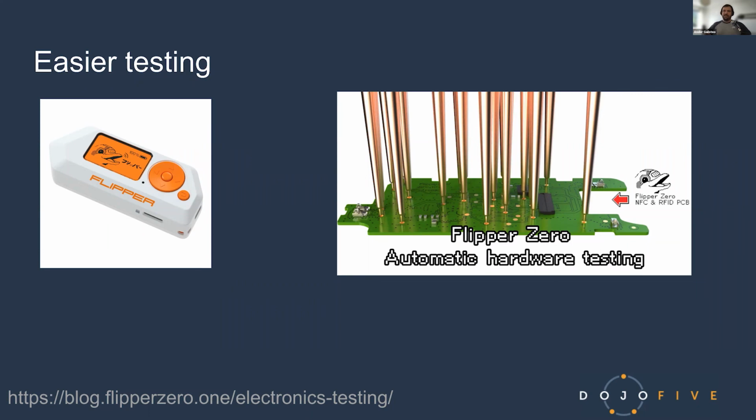Probably you want to have some testing points on your hardware that will make it much, much easier to test later on. Probably you want to make sure that at least one interface is used just for debugging. It could be serial, it could be something else, but it's usually serial because it doesn't require too many GPIOs. You want to make sure that you know what interfaces are going to be used in which stage of the process. And what these guys are doing here is basically they have a hardware in the loop setup in order to test the receive boards.